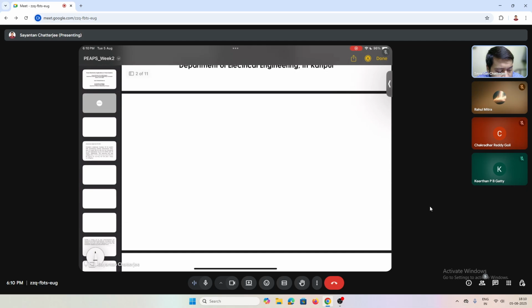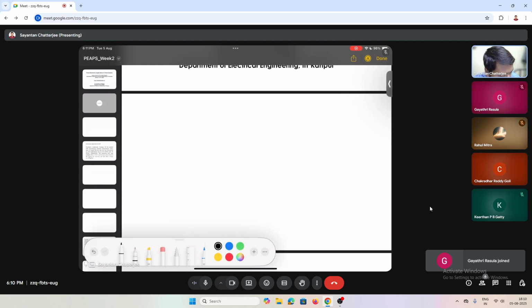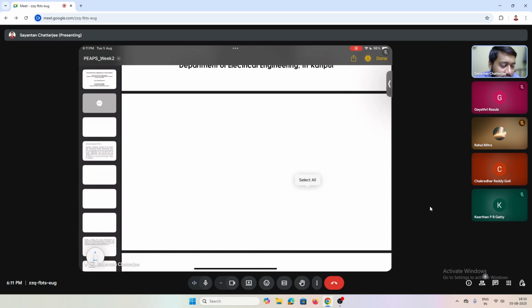Another thing is that many of you might have heard the term Ferranti effect, right? Anybody aware of the term Ferranti effect? Yes, sir. If the receiving end voltage is greater than the sending end voltage, that is called the Ferranti effect. Yes. And under what circumstances does this phenomenon occur? Any idea? Otherwise, we'll discuss.